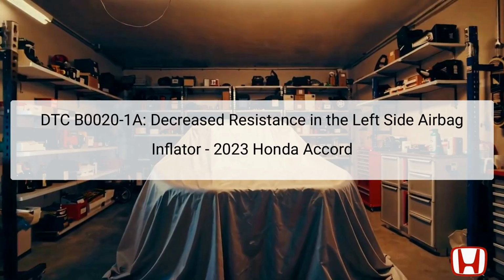The DTC B0020-1A indicates a detected fault regarding decreased resistance in the left side airbag inflator. This error code is specific to situations where the voltage on the detection line within the supplementary restraint system (SRS) unit falls below a specified threshold. If this occurs, the SRS unit assumes there's an anomaly and subsequently generates and stores this fault code.